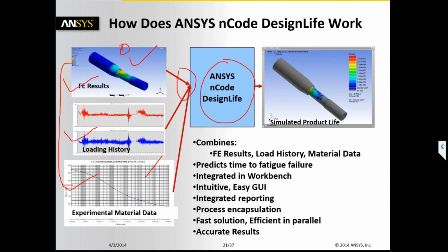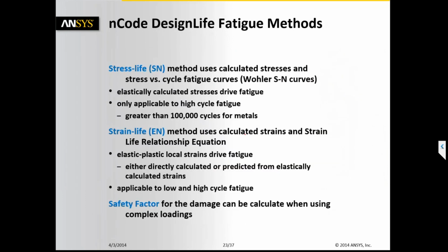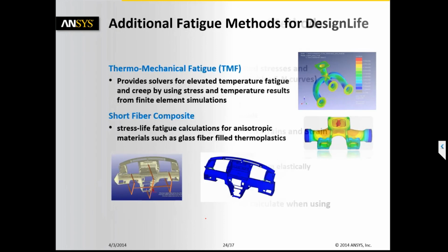So based on these three inputs, nCode will compute the damage as well as the required life of the component. This is also a process automated where, if you are evaluating a design or the fatigue evaluation criteria based on certain steps, you can use the available boxes and build your own evaluation criteria within the nCode environment. Once this is done, you can use it for SN curve based approach or EN curve based approach, stress approach or strain approach, and also damage calculations based on the safety factors.